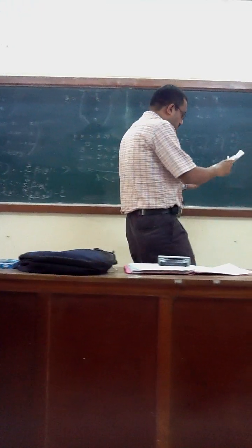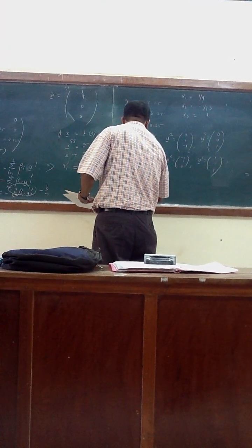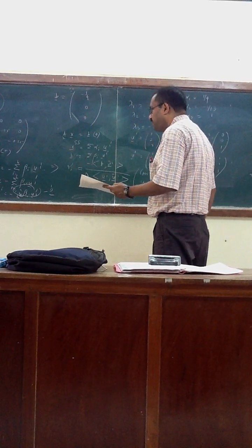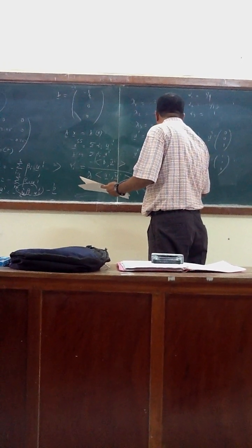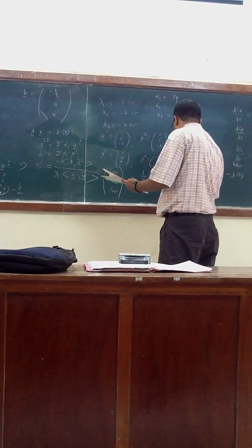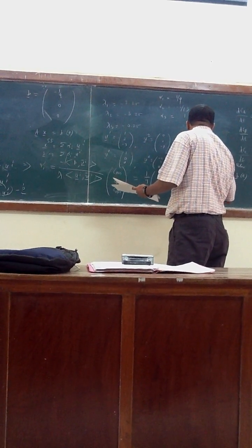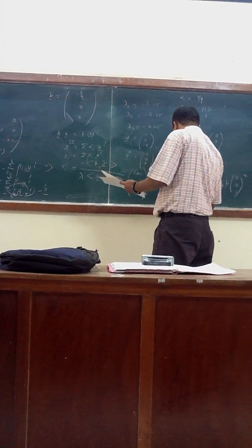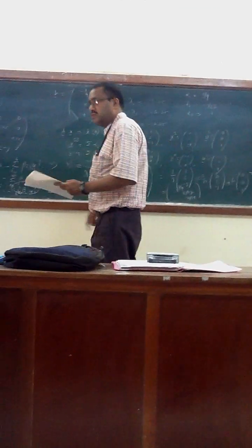So if you see the steady state values, CA SS, CB SS and CC SS, it is the summation of alpha i u_i: 1 by 9 times U1, which is 1, 2, minus 3, plus minus 2 by 30 times 0, 1, minus 1, plus 1 times 0, 0, 1. This will give the final answer, 1 by 9, 8 by 117, and 32 by 39. So these are my steady state solution.